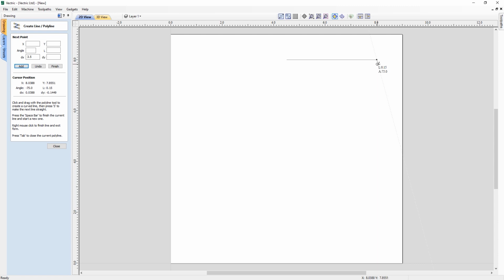Next, I know that I want a line that is 7 inches long in negative Y from that position. So I will be able, in this case, to use the 7 key on the keyboard. I press 7 and return the Enter key, and that creates a line for me there. Next, I want to have a similar 7-inch line going along an X, which I can then press 7 and return once more.